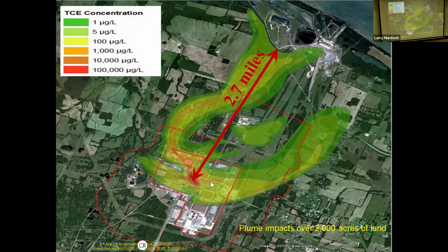The groundwater also is flowing this path here. So in this vicinity, this is what's called a groundwater divide, because on this side of the divide, the groundwater flows that way, and then on that side, it flows this way. And you can see two plumes as a result. There's probably another one here that looks like it's probably not fully understood, because there probably is some kind of connection. There's also another little plume here, and you see how it goes and just kind of stops.